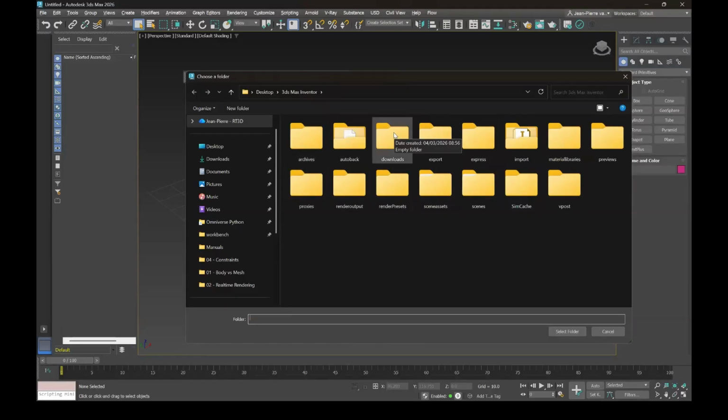And every folder has a purpose. If we archive the 3ds Max scene, you can compare the archive with Pack and Go in Inventor. In Inventor, if you want to archive your assemblies, you utilize Pack and Go. It's a similar approach in Max, but we call it an archive, and the resulting zipped archive file will be stored in the archive folder. There's also an auto backup, so Max will create an auto backup file.